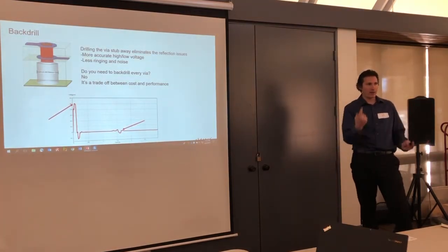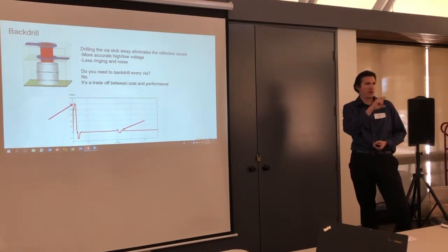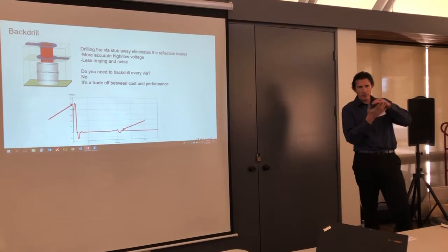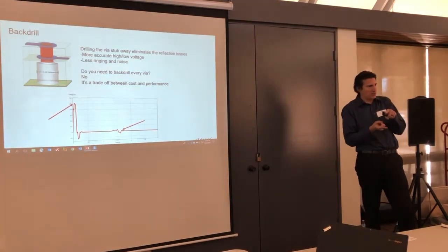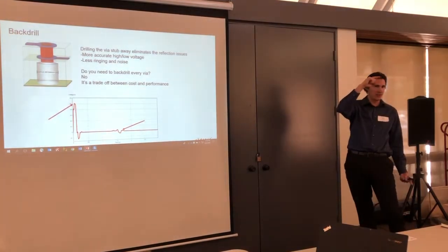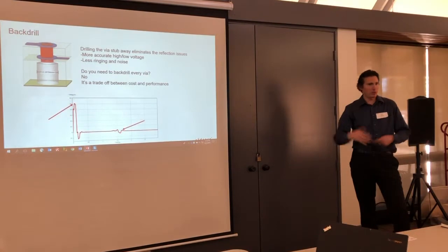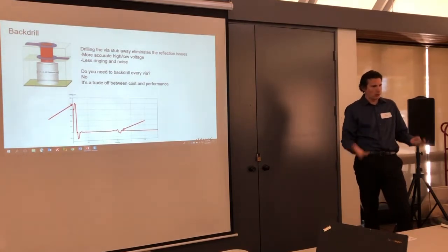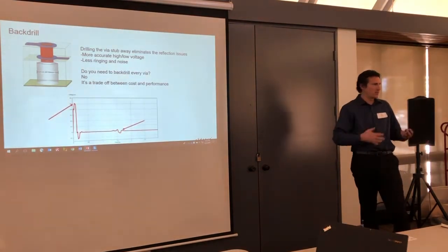What if instead of back drilling everything, I just got rid of every stub that was greater than this distance? Your SI guy might come in and say, you know what, even though you have a 10-layer board, I just don't want to see a stub greater than 2 layers. Maybe let's just back drill all that stuff, so you may have some stubs, but none at a distance enough to cause a problem. You wouldn't want to blindly back drill and assume it's going to make everything better, because then you spent money on something that maybe you didn't have to.